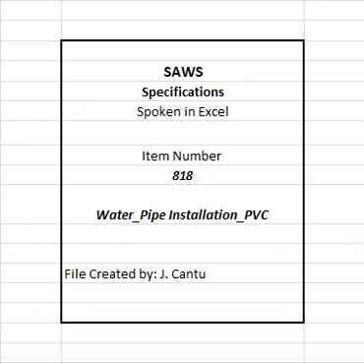818.6 Measurement. PVC pipe will be measured by the linear foot for each size and type as follows. 1. Measurements will be from the center line intersection of runs and branches of tees to the end of the valve of a dead-end run. 2. Measurements will also be between the center line intersection of runs and branches of tees. 3. Where the branch is plugged for future connection, the measurement will include the entire laying length of the branch or branches of the fitting.